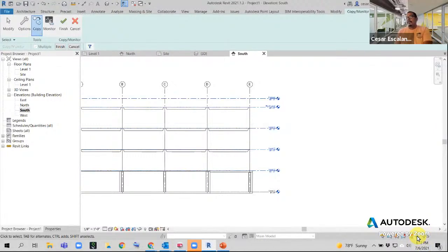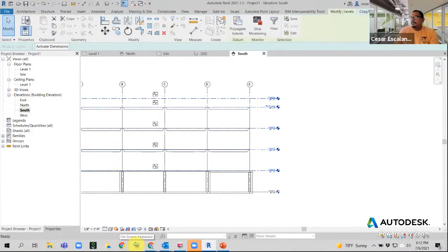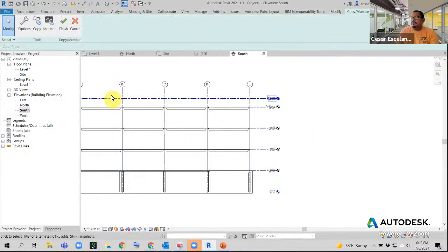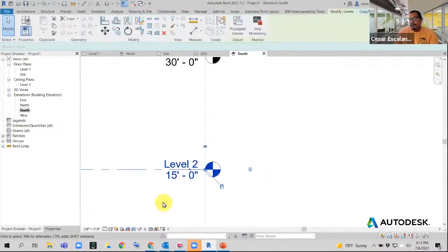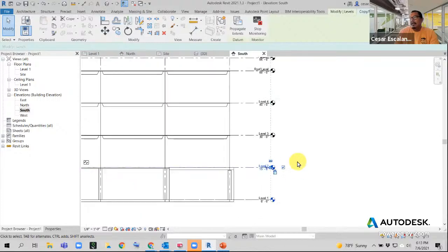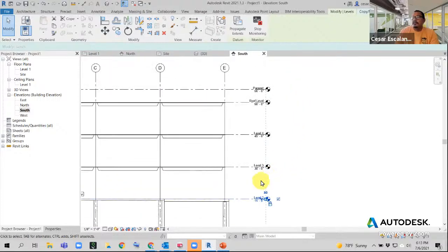And now I'm going to finish the selection. So just click the multiple selection button. It's this finish button in the options bar. And then notice how now I have to finish. Well, I'm going to stop there. Don't finish this yet. But notice that now I have my levels in my floor plan, in my model, aligned with the structural ones in the background.